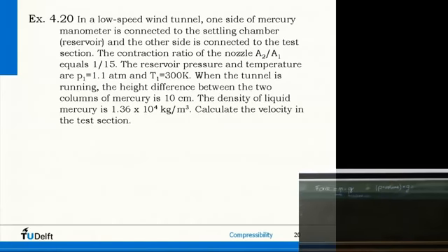What is the volume of the column? A times h, perfectly. Because we have a column here. It's h high, and it has an area A, so the volume is A times h. So the force is rho A h times the acceleration g.